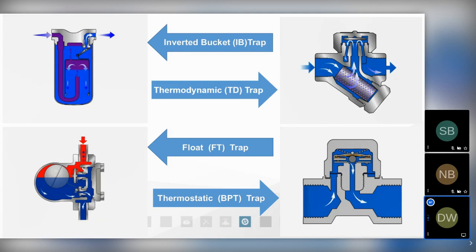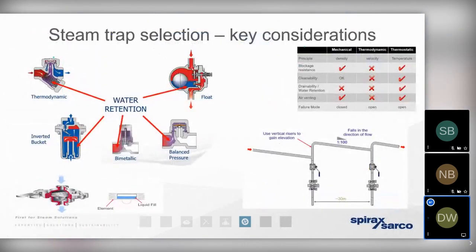But when we want to remove the condensate on the clean steam side, we need to remember, first of all, if we're distributing clean steam downstream of the clean steam generator and ahead of the process, we'll be doing so in 316 stainless steel pipework. Why? Because we don't want to reintroduce any risk of corroding carbon steel. And it also means that we want to guarantee that we're removing condensate at all times. We're never holding any condensate back because that can impact upon that critical dryness value.